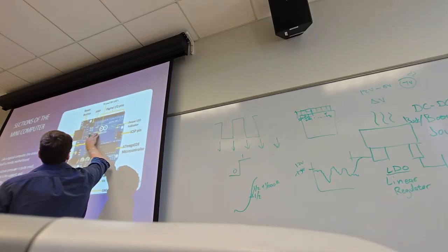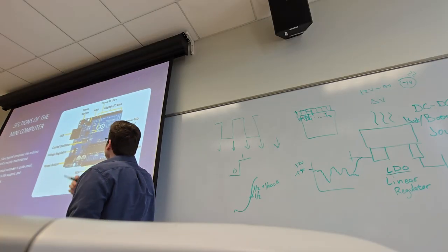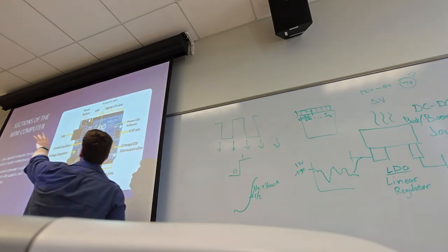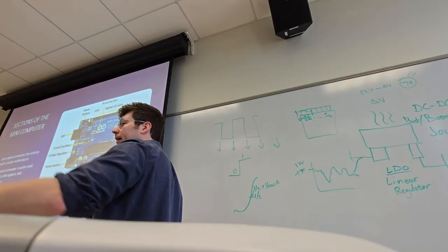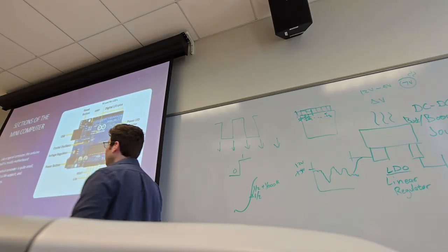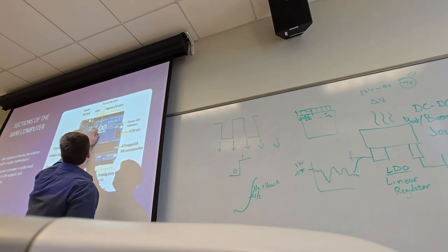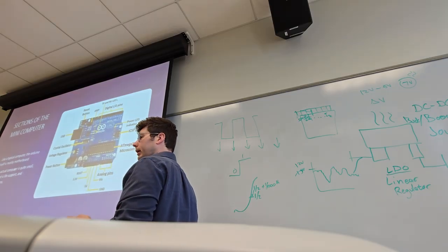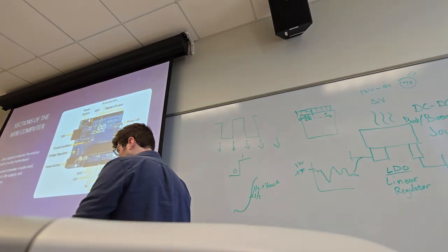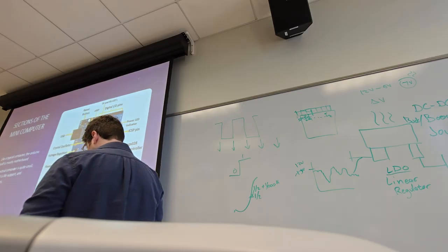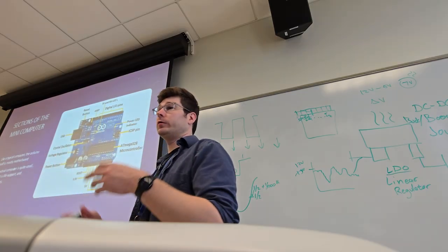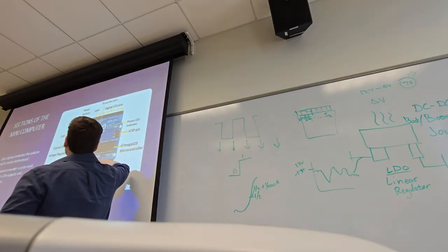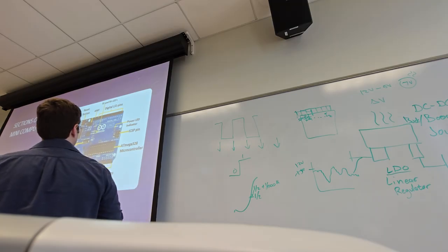Most devices will have TX and RX pins, really useful. It essentially is just, are we sending bits to our chip or from our chip? Really useful for seeing, is it alive? Essentially, is it taking data? Is it sending back information? Things like that. We also have a user accessible LED. Just like our onboard PLC LED or user LED, Arduinos also have built-in LEDs, mostly for debugging, right? Am I alive? Is the process working? When we're sending a message, blinking a light, things like that. We also have just a general power LED that's always on as a keep alive signal.